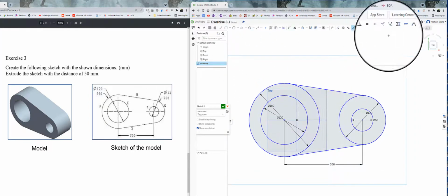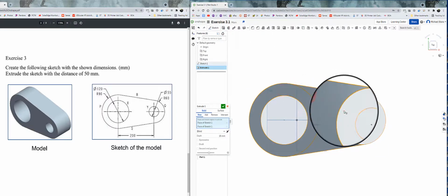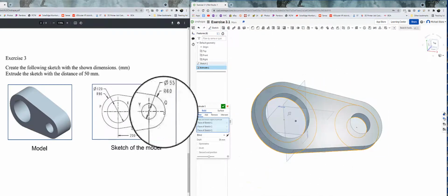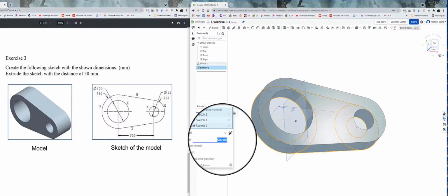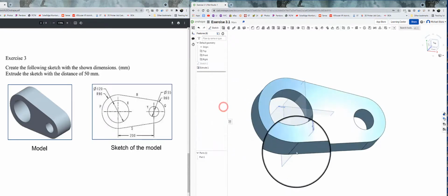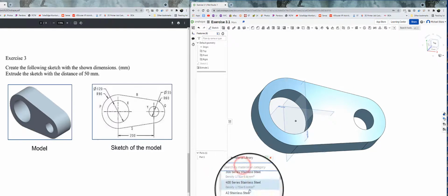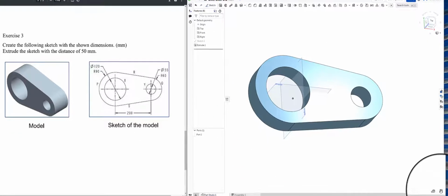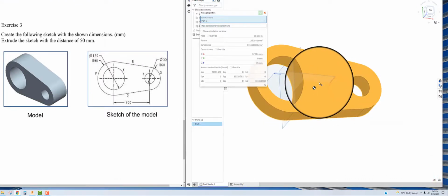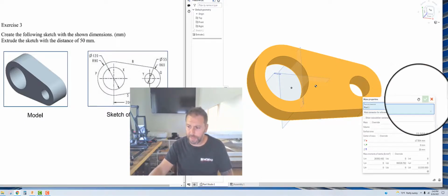That is that part. Same thing, finish sketch, extrude. And they want an extrusion of 50 millimeters. And the same thing, right click, assign material, and that aluminum 6061. Go, and we could display the properties here. Then we click on it, and there we have it. That's that part. Screenshot all that. And there's your first 3 parts in Onshape.